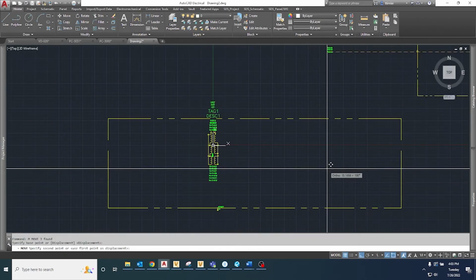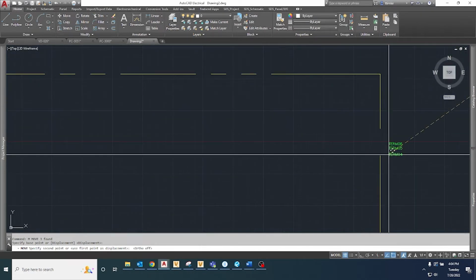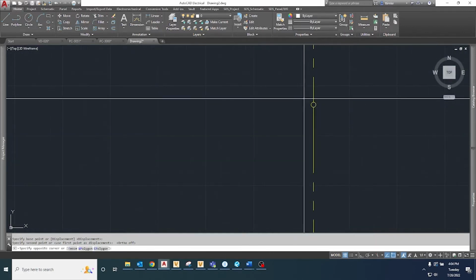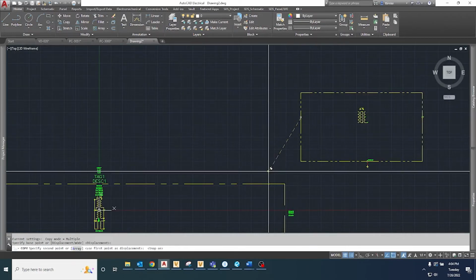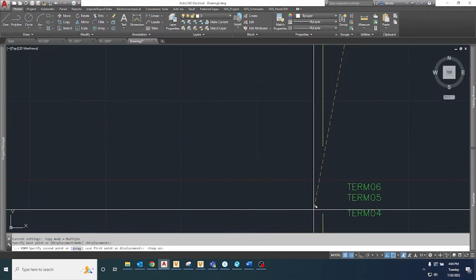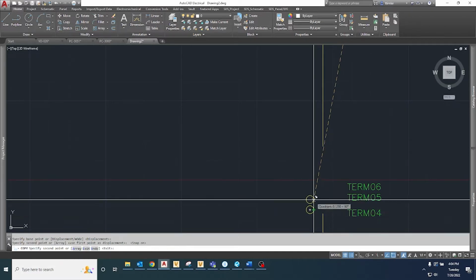This is a complicated block to build because there's more than one way to approach building a transformer symbol like this. My initial plan was to create this as a 3-line parent symbol and then create the bushings as secondary child symbols. The idea being that this would give me a little bit of flexibility in positioning the symbol on the bus, depending on how many CTs I have associated with it. But I think I'll include the windings into the parent symbol instead.